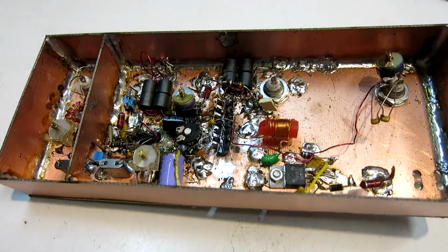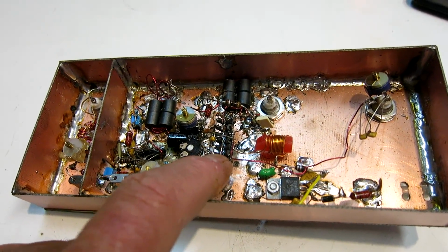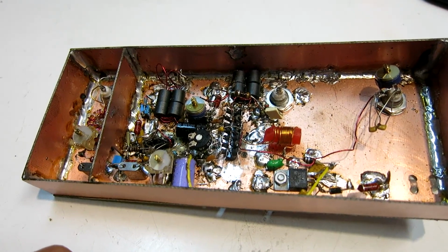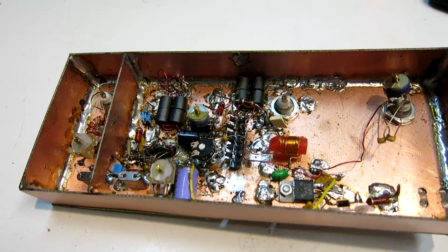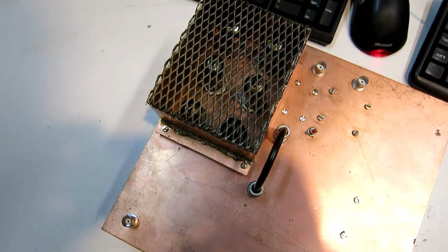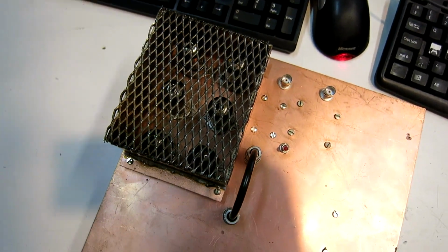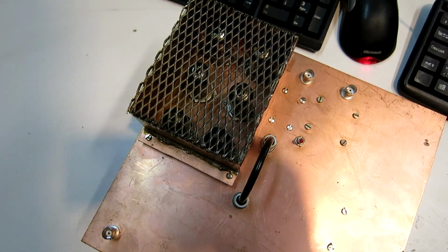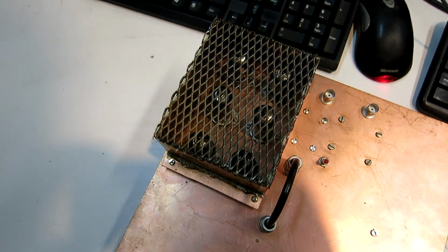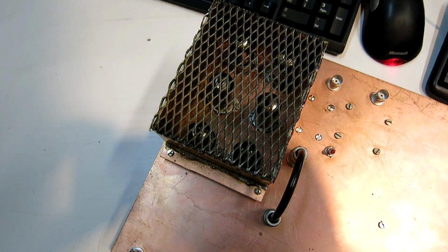Then I decided maybe it is the capacitance of the transistors, the output capacitance, that could cause parametric oscillations. So I skipped this. To eliminate varicaps, I made this thing. There are 6 PCC88 tubes, which means 12 triodes in parallel. And then I send that in grounded grid configuration.